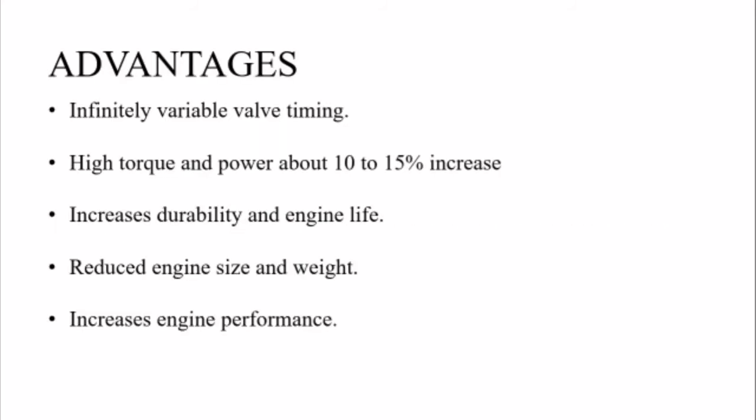Coming to the advantages, there are many advantages. The first one is infinitely variable valve timing. That is, flexible valve timing is available by using camless engines. The second advantage is that we can produce high torque and power, that is, about a 10 to 15% increase in the torque and power. The next advantage is that the engine life and the durability increase.